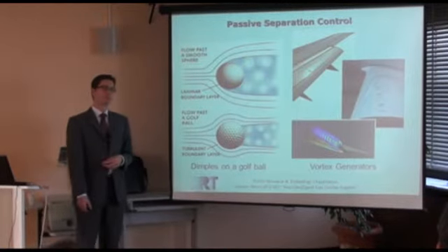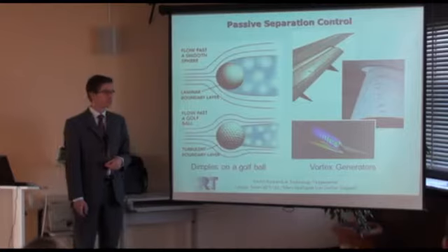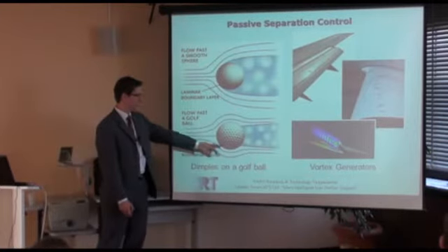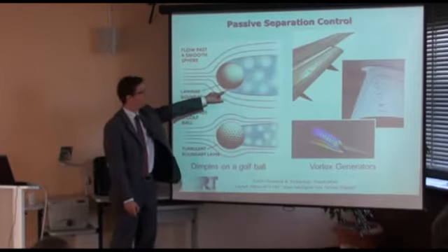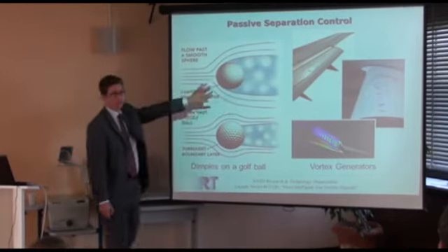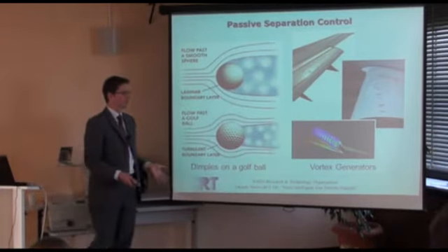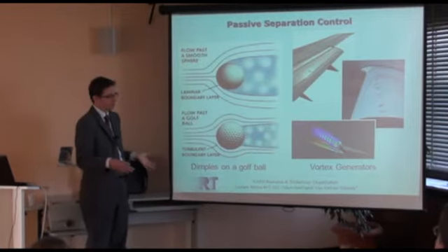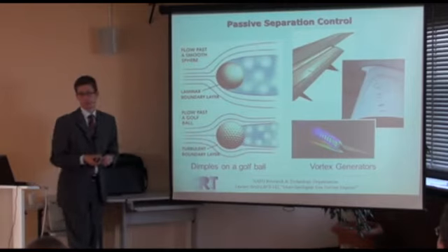The same is true here with this vortex generator on the airfoil. They create an additional drag, but it's preferred over having a big separation. So it's true, the pressure losses in this part are higher than in this part. Okay. But the net effect is seen here in this way. And you could imagine with this wing, if you get the flow attaching and then you've got a certain turning of the flow, then you have got a higher lift. That's what you want to get.